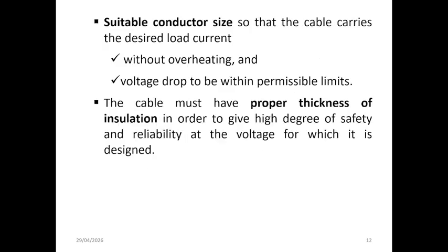Okay, this slide highlights two key design requirements for underground cables. First, the conductor size must be properly selected so that the cable can carry the required load current without overheating, while also keeping the voltage drop within acceptable limits. Second, the insulation must have sufficient thickness to ensure a high level of safety and reliable operation at the specific operating voltage.